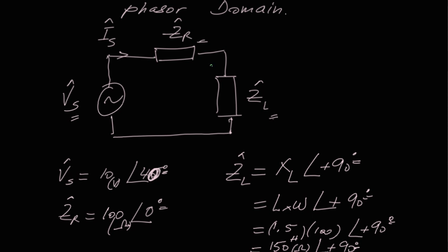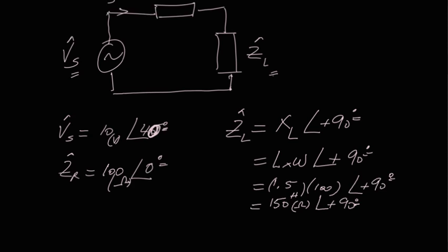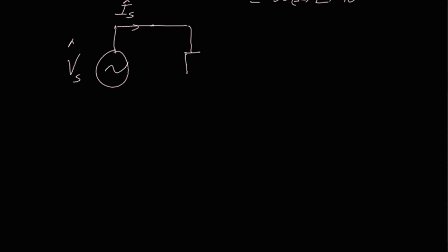Furthermore, this is a very simple series circuit. And remember, impedances follow the same rule as the resistances. So we can now come back and simply say that the same voltage supply giving us the same current, Is, is feeding into one impedance, we're going to call it ZT, which is simply ZR plus ZL.